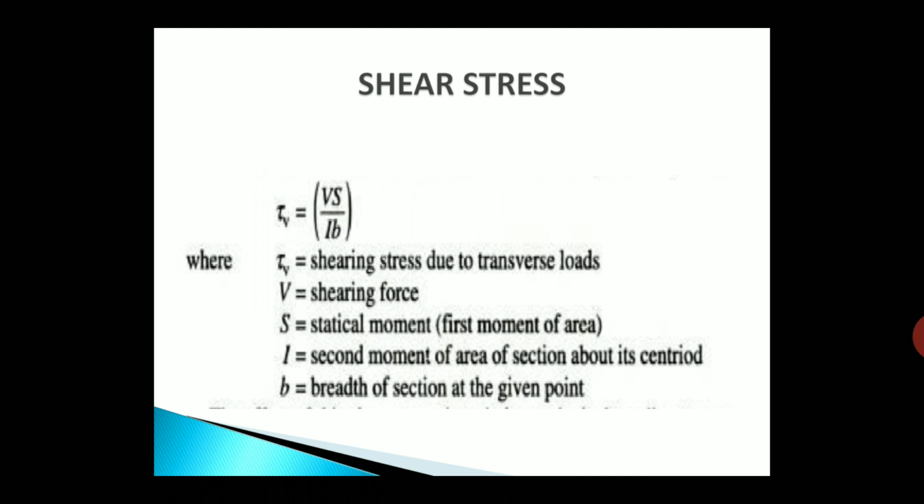Then the shear stress. If you recall your RCC, we used to compute the shear stress tau V equal to Vu divided by Bd, where Vu was the maximum shear force and Bd was nothing but the area of the section.